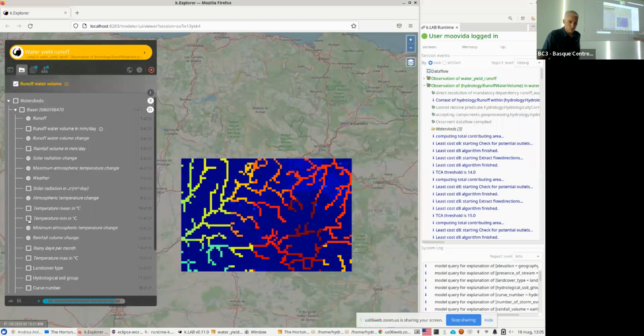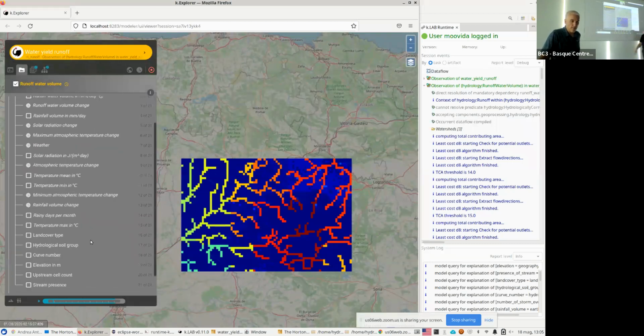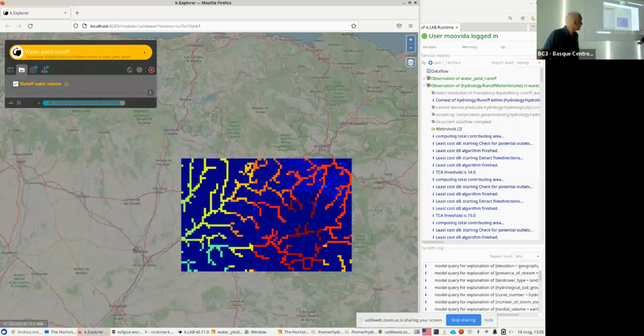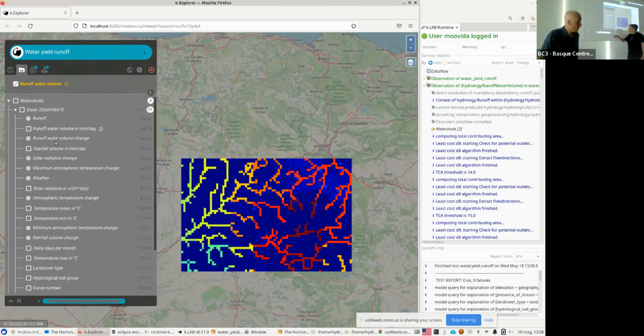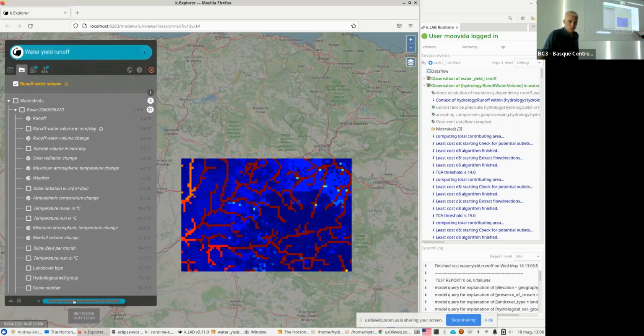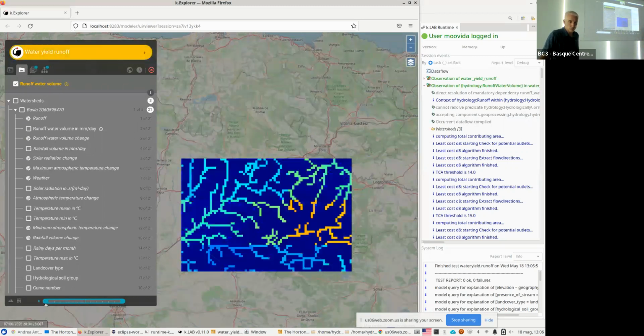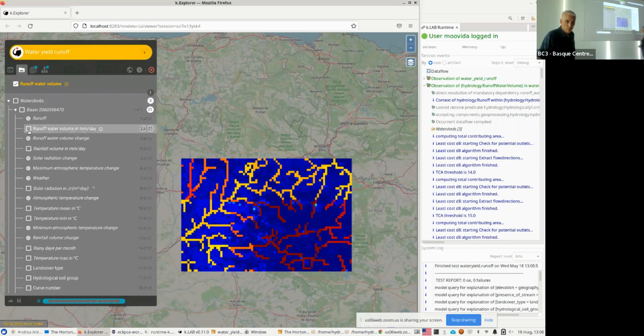It pre-exists the time. But runoff, and this is all part of the semantic analysis that you have to do for these models, runoff only is a product of the process of moving water around, so it's a process of precipitation. So it only exists when the time is actually running. So you need to click on that bar, the bar over here, in order to move out of the initialization state, because runoff is no data at that stage. So if you look at that now, you can actually play the movie of the runoff in this region, which is the runoff of the 3 watersheds. So it's computed properly. The points here will be computed knowing that the outlet is over here.